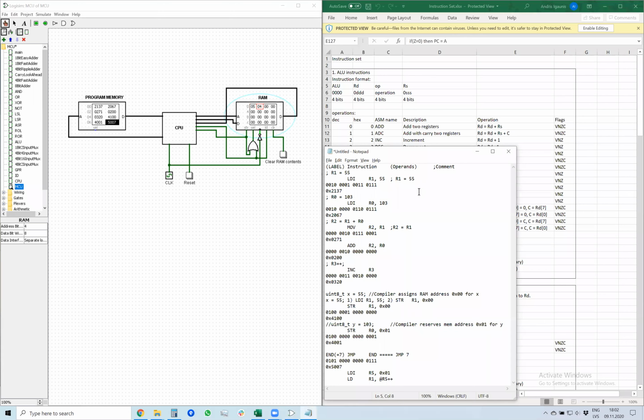You will have to write a program which reads the two numbers into registers, then multiplies them and writes the result into the next register. So 5 times 4 is 20, which is 14 in hexadecimal. I would click the clock until it says 14 in this memory location. We will do it next time, and you will have similar homeworks later.